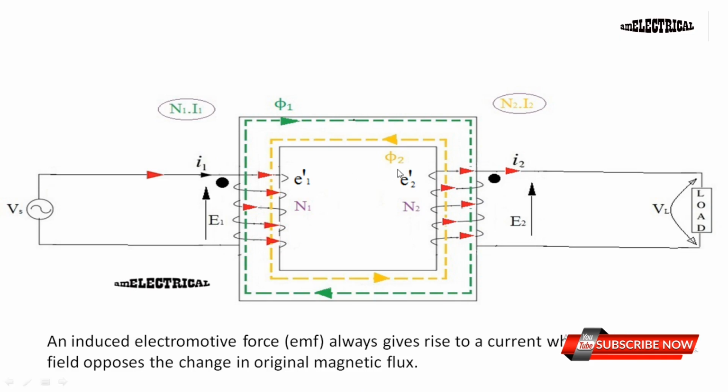Now this flux phi2 will also link the primary and secondary winding. So it will also induce some EMF, say E1' and E2', in primary and secondary winding respectively. Listen carefully. What's happening here is, first, due to phi1, E1 was induced in primary, and now again due to phi2, E1' is being induced in the same primary winding, but in opposite direction.